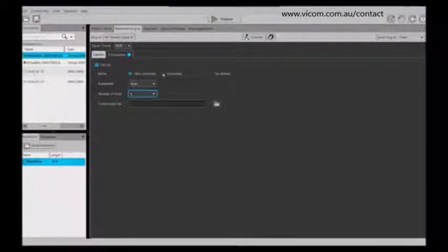Now we also have the ability to cascade S parameters, so that if you have more than one component, you can add all the components that you want to use. These S parameters have to be of the same port number, but you can add plenty of them to your system, so if you have several filters or several other components in your system, you can add them as S parameters.